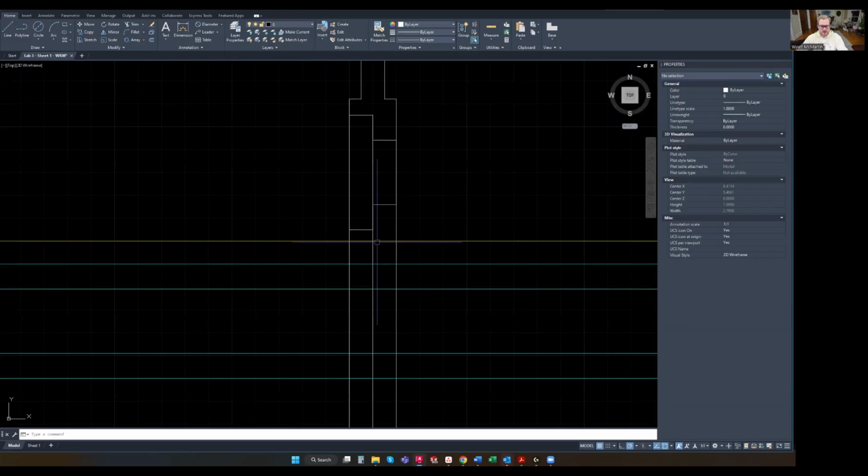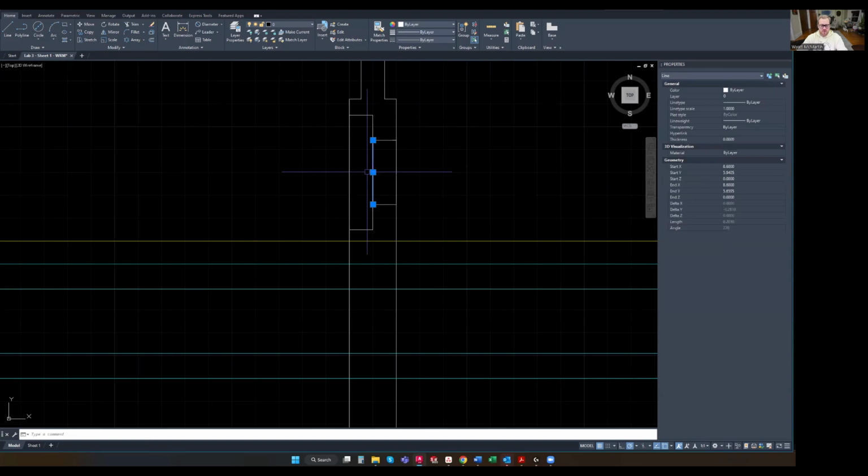And at this point, you can really see it coming together here. So I'm going to go ahead and delete that. Just delete that other center line as well. And at this point, just draw a line connecting where the pilot hole meets the counterbore, just like that. Don't draw it overlapping like this because it looks a little funky later when we make these dashed. So just connect it just like that.